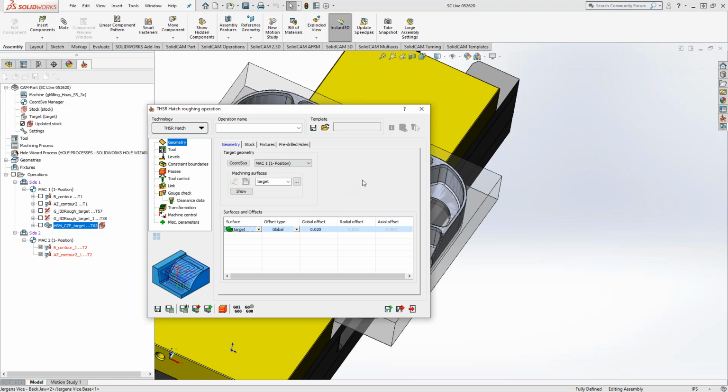So we've had some customers in demos and training who asked, what if there are separate surfaces that have to have more or less material than other surfaces? This toolpath will allow you to do that. You'll be able to rough out the entire part, but leave, let's say, 20 thou on certain surfaces, and then another set of surfaces maybe just 10 thou. So it actually will keep track of that for you and do different roughing on different surfaces.